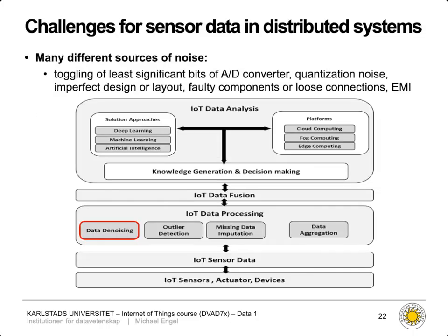Right. So what we have achieved now is a signal that's time discrete and value discrete. And of course, if we have discrete time steps, we can ask our computer to read a value at these discrete time steps, and that's exactly the digitized amplitude, the digitized value we've just produced using our analog digital converter. So now we just have an array for each time step, and in this array, we have a digital number representing our digitized value at that point in time.